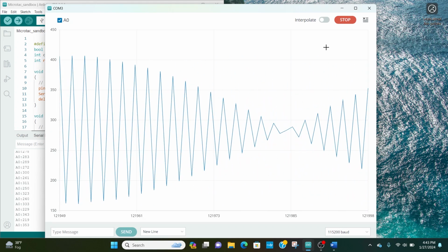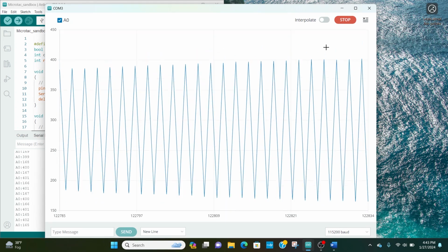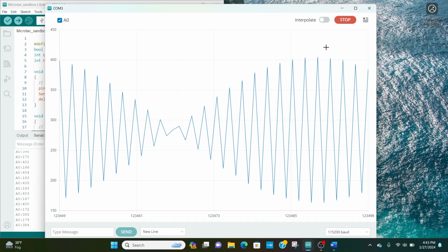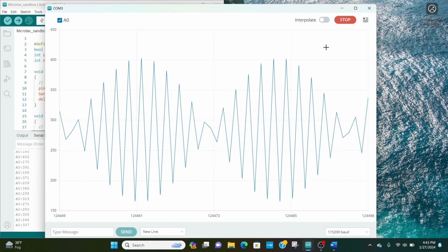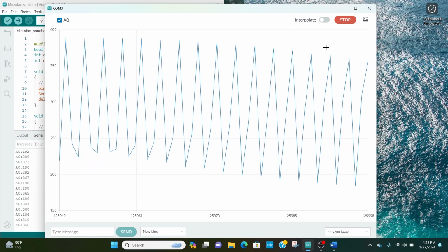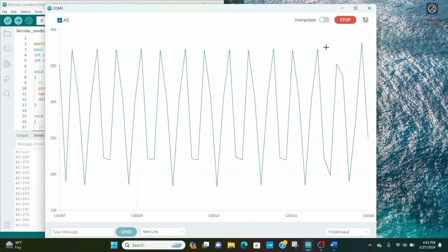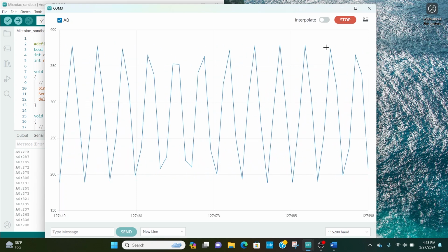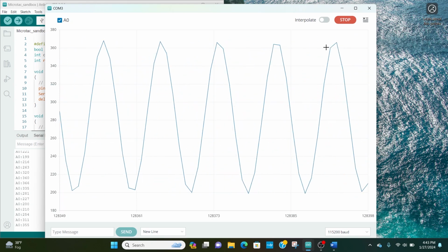There's a very low frequency component there that's not real. That's not part of it. It's just errors coming from data acquisition. And if I exceed around 5 kilohertz, let's get this up above the Nyquist criteria, that distortion looks like it's smoothing out, but what's happening is I'm getting an erroneous signal.